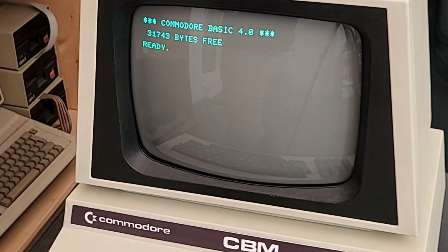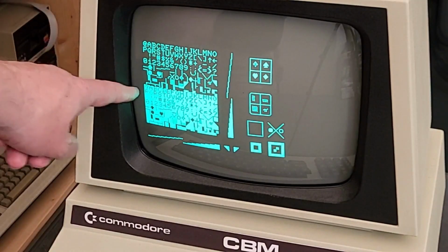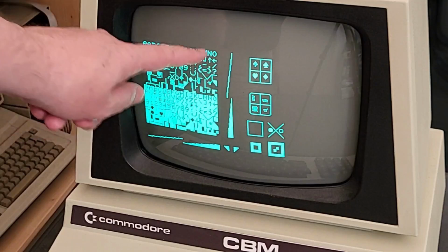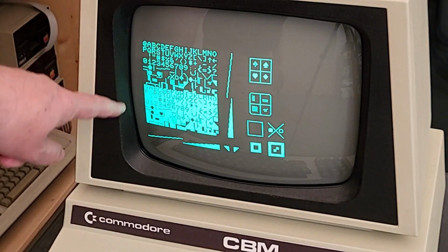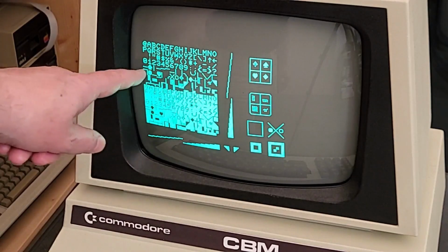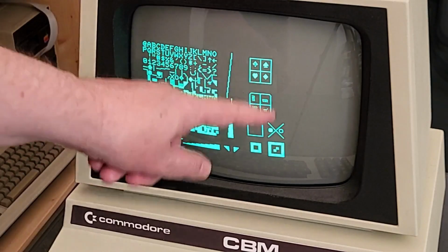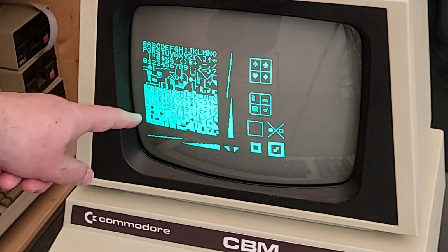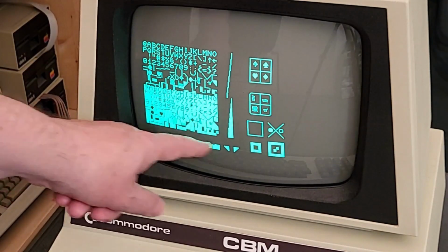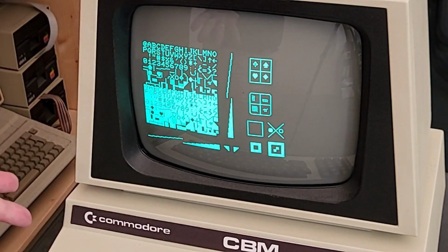What we've learned is that the Commodore PET has a fixed character set that is in ROM and it cannot be modified. So let me show you how that character set looks. You see here, this is the character set that is in ROM. It's only the upper half, 128 characters, and the other 128 characters are inverted in hardware. So using all those characters, this is uppercase graphics mode. You can change that to lowercase, where some of the graphics characters go away. But this is uppercase graphics mode, and you can use these graphics characters to create boxes, lines, and so on. So this cannot be modified, but